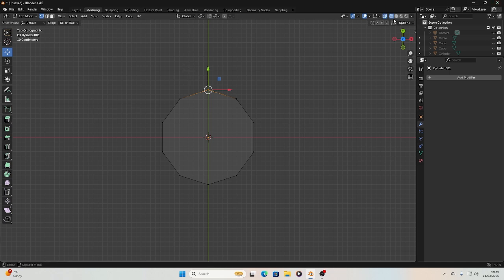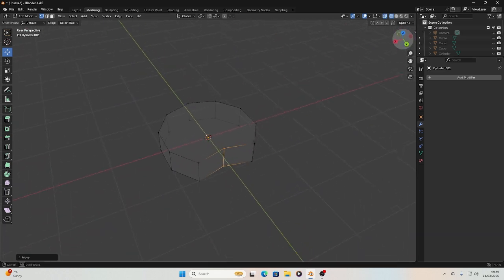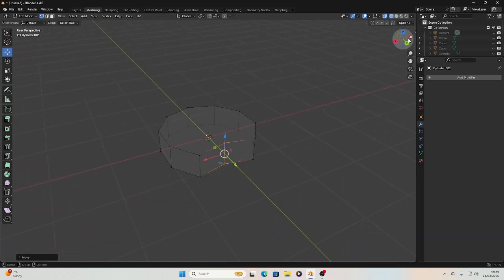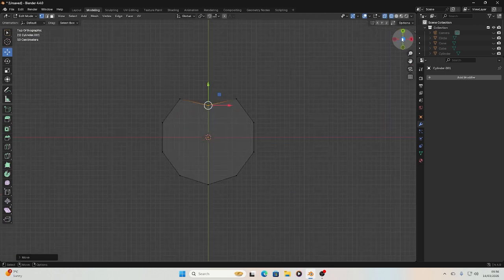And if we then, so if we just switch between those two for a second just to remind ourselves, then if I click and drag the net over that vertice, this time it will move both, because in wireframe mode it will select all the vertices in that area rather than just the one that we can see. So Control Z is undo, and what I'm going to do now is hold down the Shift key and I'm going to click and drag around every other one.